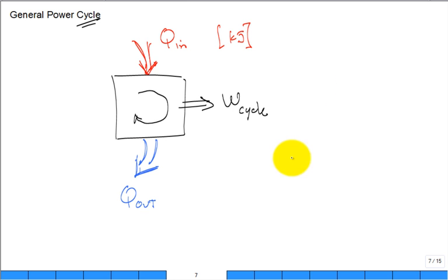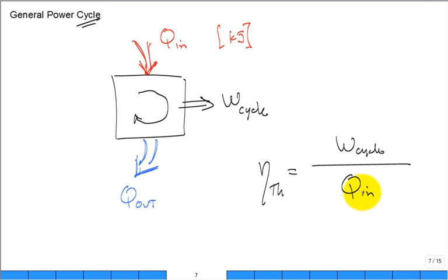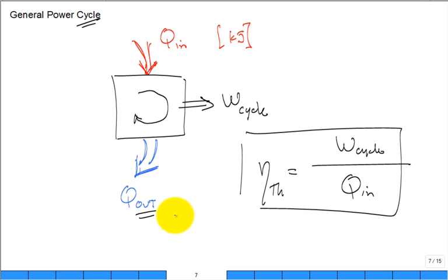So we have the efficiency, the thermal efficiency of a heat engine is a ratio of what I desire. What do we want from a power cycle? A large net work out. What do we have to provide to make it work? We have to provide the heat in, not the heat out. That's a waste. It's just what you have to provide to make it work. So here is an efficiency of the cycle. And then they could play all kinds of games. Given this, given that, whatever, make some calculations. Let's see if I have a problem on the next page.